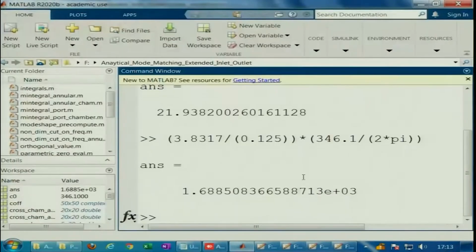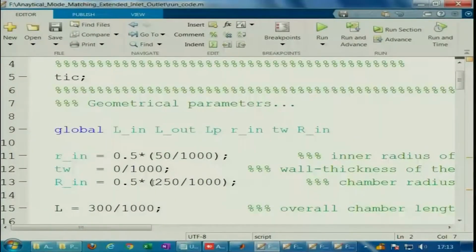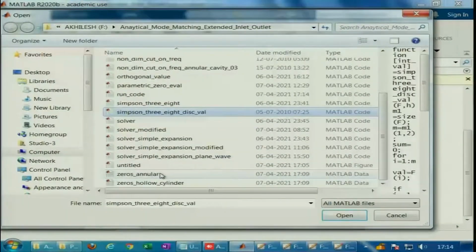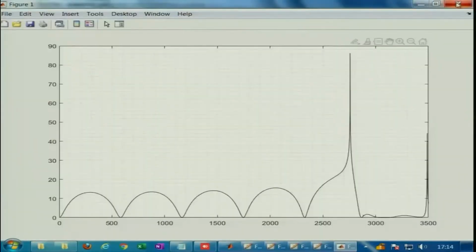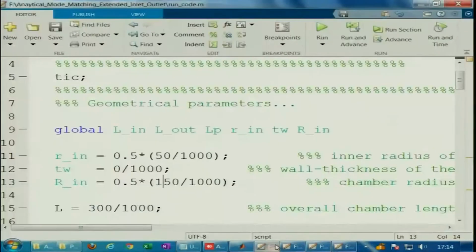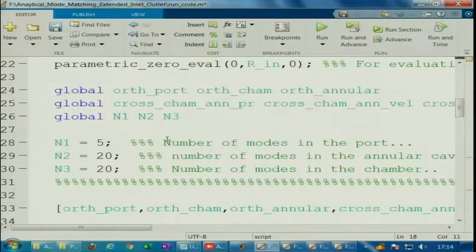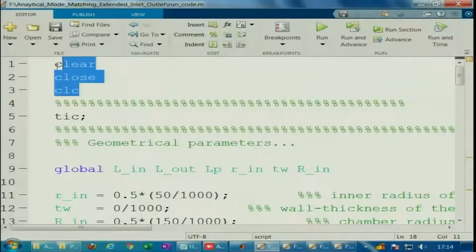So, I am going to close off this file and now do a simple case. Let us perhaps consider this 250 or probably 150, because we have saved this file, the untitled. So, we will compare it with this case and see a dramatic improvement that it gives. Okay, the expansion ratio is only 3 or area ratio is 9. The maximum transmission loss that we get is 20 log m by 2, but with extensions, let us say half into half the extension. So, what is half of 300? This, and this is 75. Now, it is going to evaluate a different file. Okay.